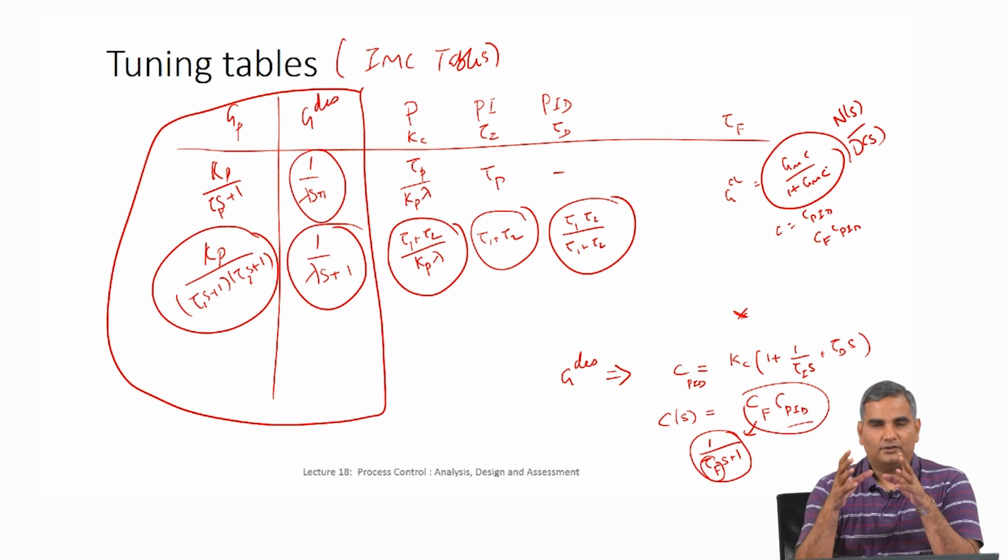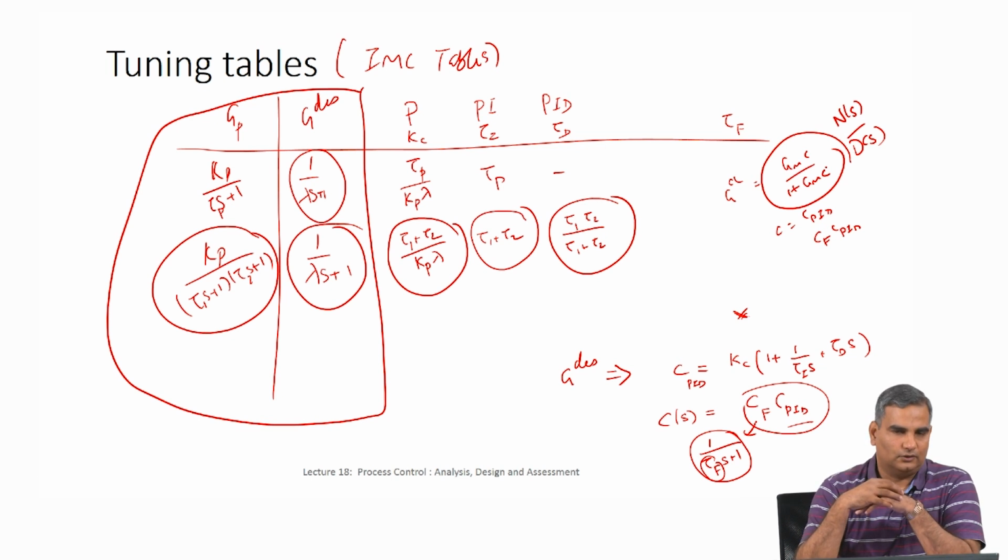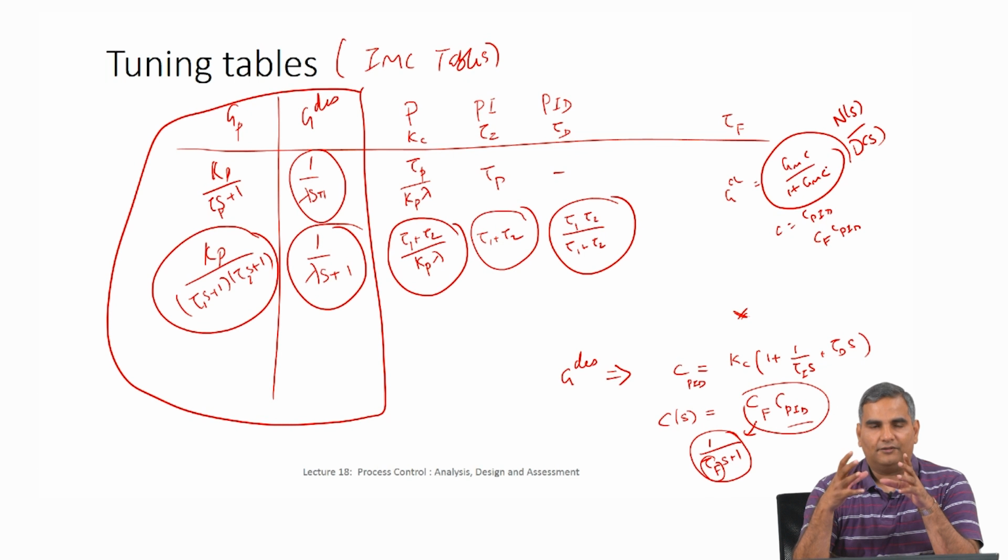And I also said when you think about state space models, you could have multiple states but you can still look at single input single output control systems. Anyway, after that we solved these state space models in time domain, and then showed that the output will be in what is called a convolution form or a convolution integral.